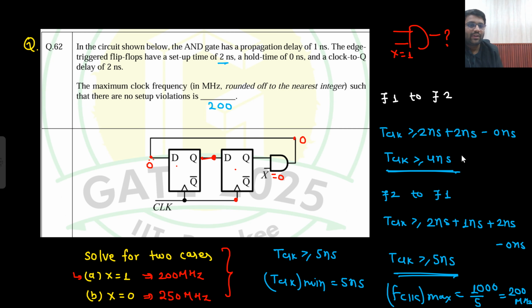A lot of people would surely have worked from here to here, and a lot of people would have done it wrong, because they don't care that this input is already stable. So always the first thing you need to check is whether the input is stable or not. Why is that so? Because in the GATE examination, a question was asked where the input was already stable. And if they frame a good question on STA, they will surely make sure that one of the inputs will be stable. Okay, so these are the things. Let's see more questions.